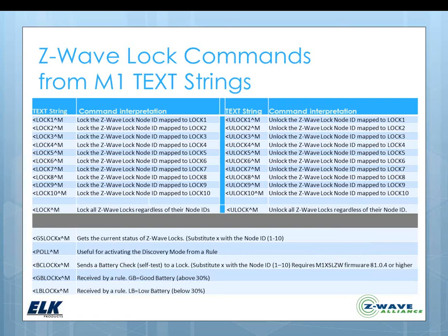In the Z-Wave world, the maximum number of devices in a single network is 231. But if you try to put 231 devices in a single network and manage that, I think you're going to pull your hair out. So we typically suggest that typical networks are 70 to 80 devices in a really big house, and that works just great. If you're going to go beyond that, sometimes it makes sense to break the system down into 2 or 3 different networks and have each controller, maybe a controller for the top floor and a controller for the main floor or something like that. But the numbers that Amy just provided will work comfortably within the Z-Wave technology.